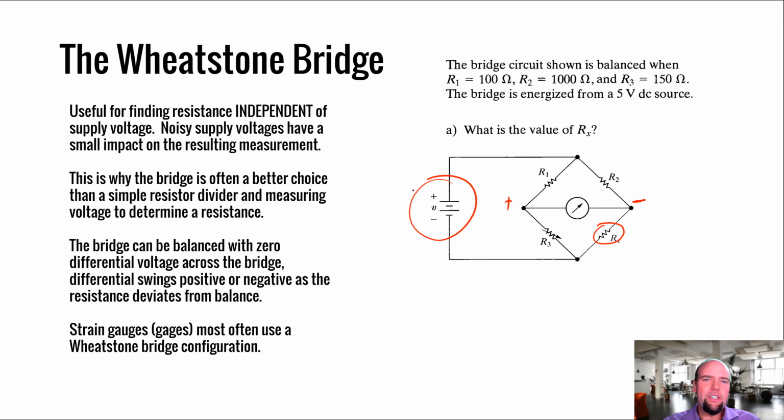But these strain gauges are typically installed in, for example, the scale in your bathroom, which has strain gauges that work like this. People build a bridge. Quite often they'll glue a strain gauge to the side of it to measure how much the bridge is flexing as it's undergoing a load or as trucks go over it or whatever. But usually with those strain gauges, you want to know how much the material is deflecting from some nominal position.